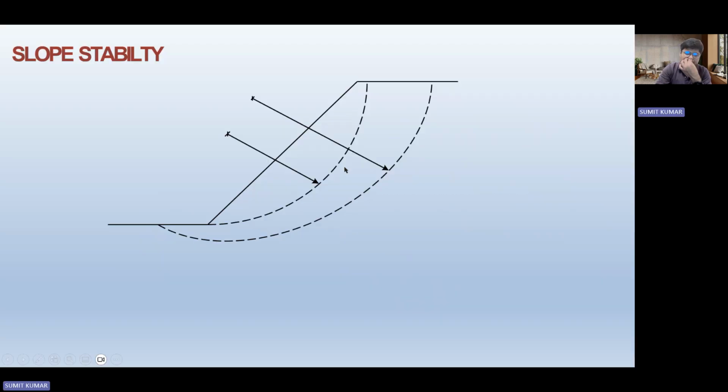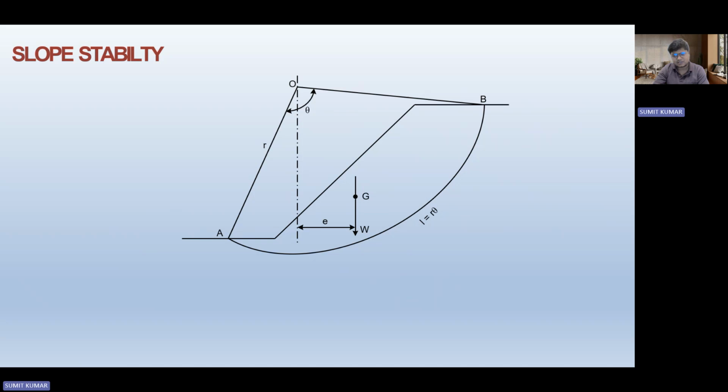Over here, the discussion I am giving is that various critical slip surfaces have been made, and afterward, by performing the calculations on the same, we conclude that this is the critical failure surface, and the factor of safety passing through it gives this specific value.